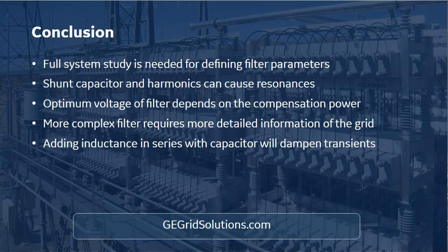Then with some of the modern wind parks, there will also be situations where no fundamental frequency compensation is needed. So they will only need filtering. This means that you have to use some kind of active solution. This is a STATCOM or something like that. Or the other approach is that you will have a passive filter. What I was now talking to you, passive filter.